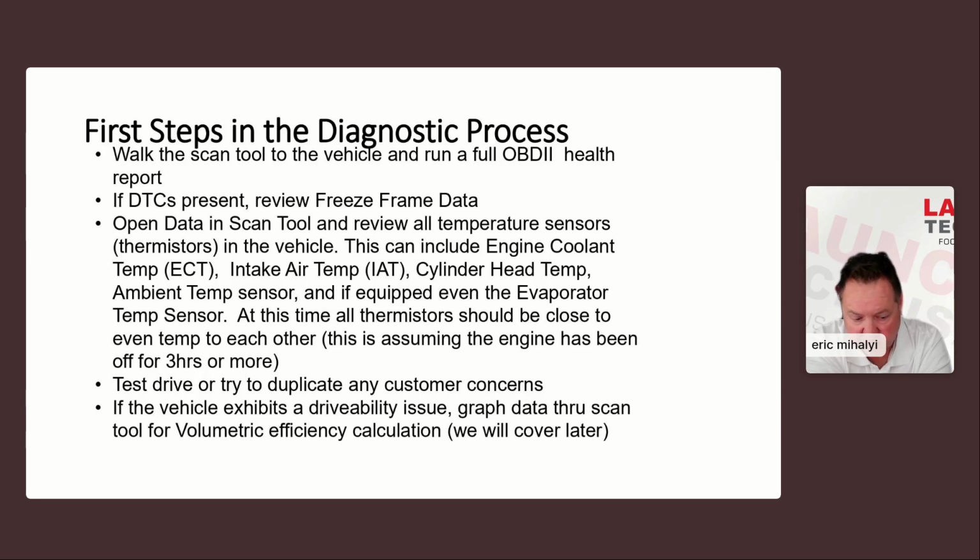Because again, whether it's the time of the injectors being on and the firing of the spark and all that stuff, a lot of it is based on the volumetric efficiency of the engine itself, right? So very, very important, right? Because an engine is a giant air pump, right? So if you have a compression problem, and it's a 6-cylinder engine, you're going to have roughly, give or take, about a 15% loss of volumetric efficiency.